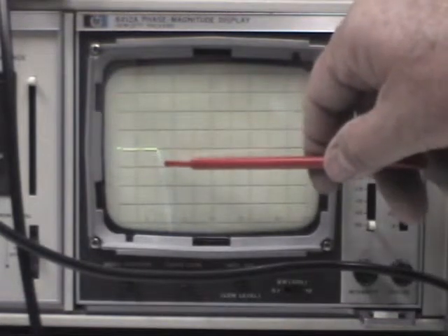Let's take and measure the frequency here where it starts rolling off, and filters are spec'd in bandwidth to the 3 dB position, so I've got a 2.5 dB per division, so I'll just roll it off 2.5 dB and we'll measure the frequency. So I'll just take it down towards down there. The way I do that is I just take the sweep generator and put it in manual mode, and now I can adjust the dot anywhere I want. I'll adjust it to right there. That's about 2.5 dB down.